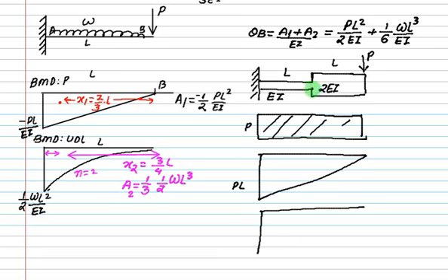And what is this value? This is PL, divided by 2EI. So the figure will deviate something like this. This one is PL upon 2EI, then it will shoot up, and finally the value here is PL upon EI. Got it? So how many figures are there? 3 figures: 1, 2, 3. Your problem will become more complicated. I will discuss this later on. Don't write now. Let me calculate YB for this.